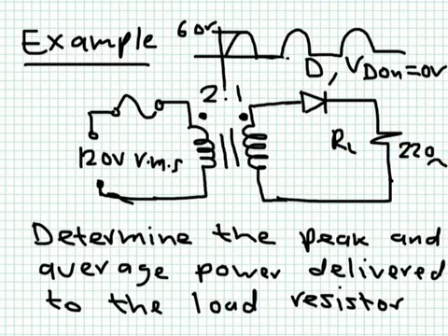Now, if you want to get the average power, it is related to the DC voltage. This is an alternating voltage. The one I'm showing you here is an alternating voltage. So if we replace this one by a DC value, and we already calculate this expression, we can determine what is the average power delivered. The average power delivered is this DC value squared divided by RL.